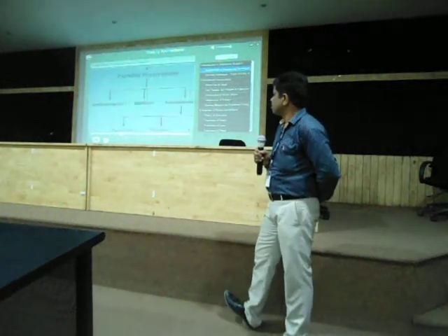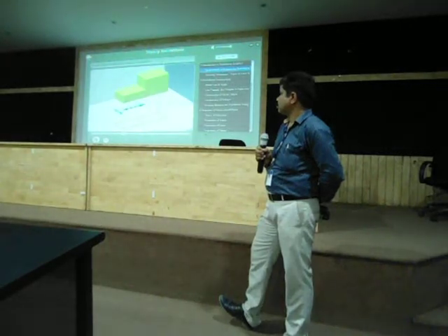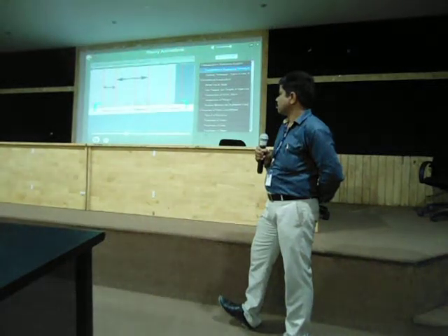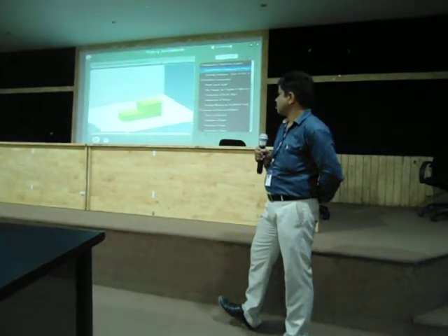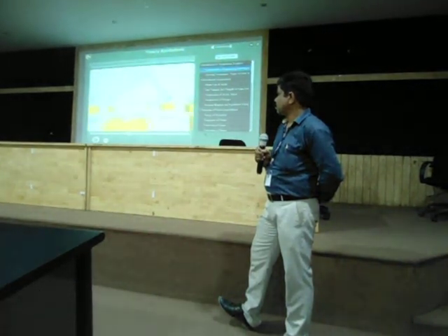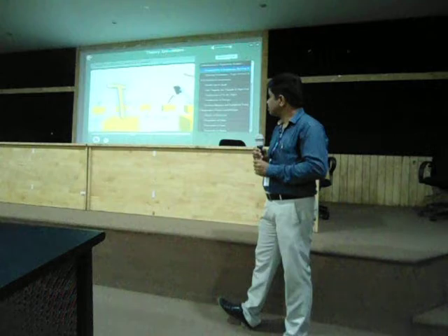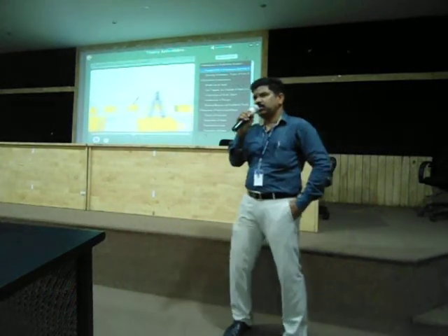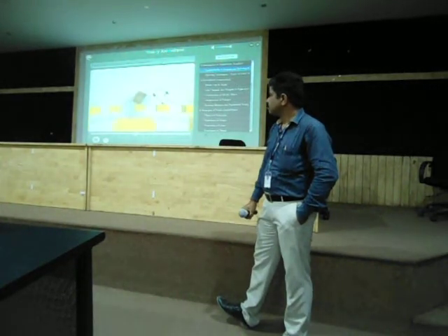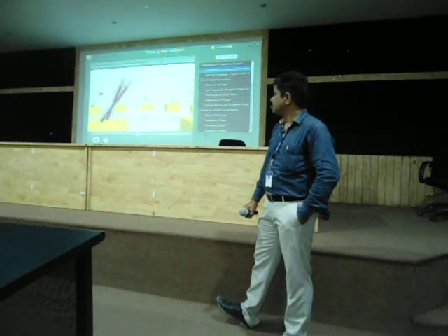We will focus on orthographic projections, where the projectors are parallel to each other and they intersect the projection plane at right angles. We will study orthographic projection in detail later. So let's take a look at important tools used in engineering drawing. Drawing paper, drawing board, drafter, T-square, compass. The T-square is used in architecture particularly. French curves, protractor, set squares, scales, pencils, erasers.